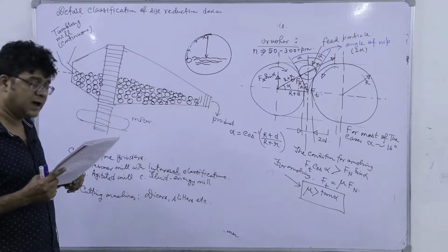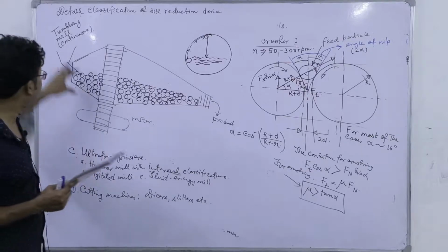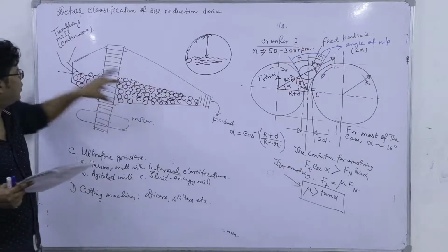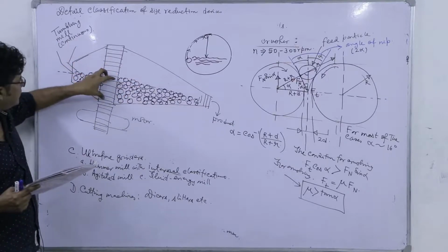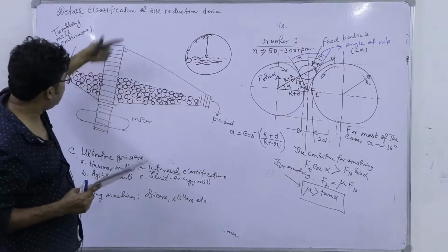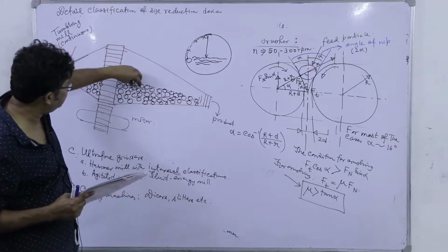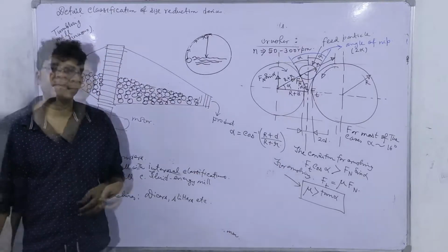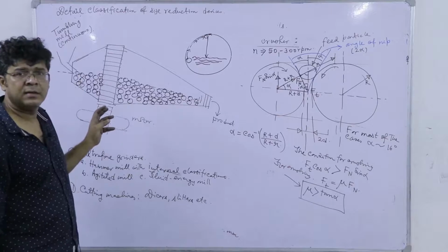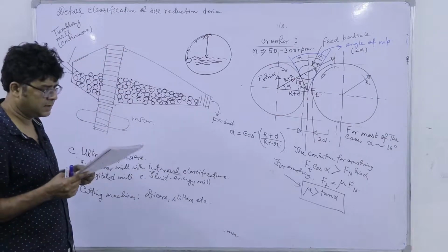The grinding may be done with dry solids, but more often it is done with a suspension, because there is a smooth flow of the slurry, right. So the solids are in suspended form, they come here, and as the mill rotates, the balls move up, get detached from the roof and create an impact on the material over which they are falling, right.